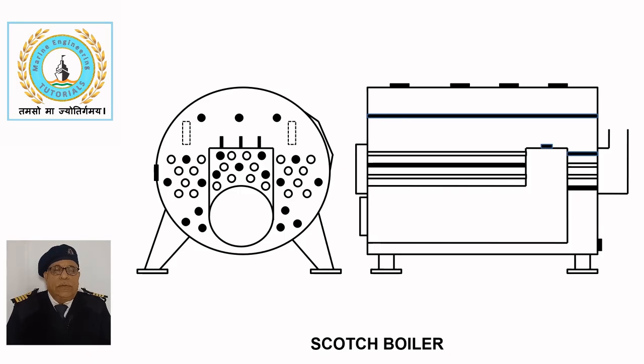Smoke tube boilers have a tank type construction, making them compact and easy to operate and maintain. Due to their limited use during the ship's port stay, they do not require frequent maintenance and major overhauls can often be deferred until their survey.